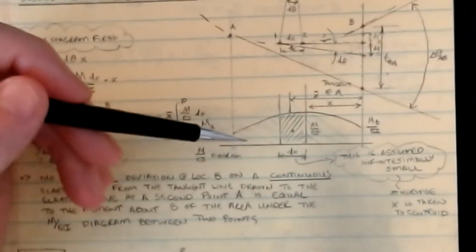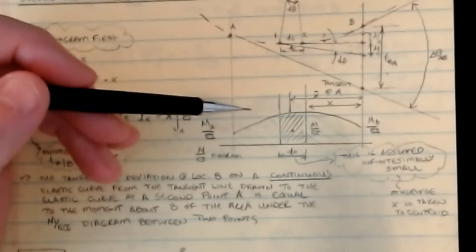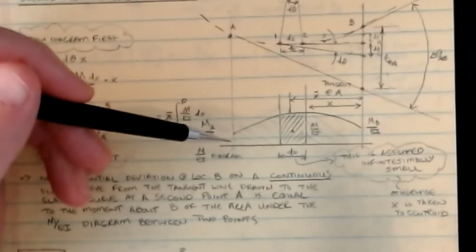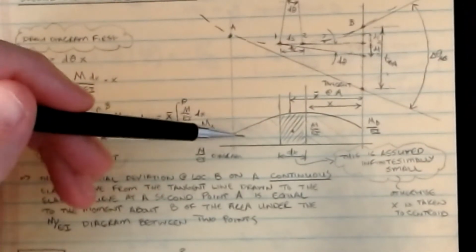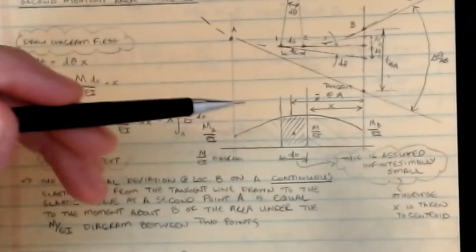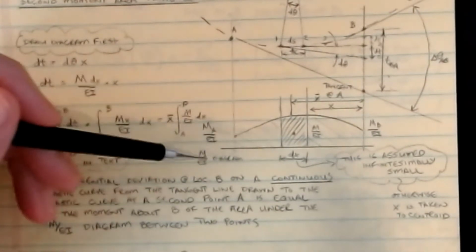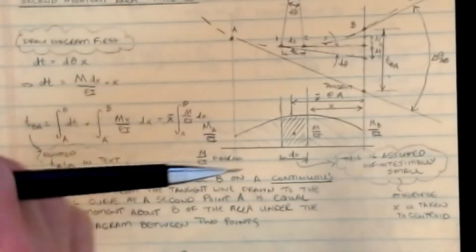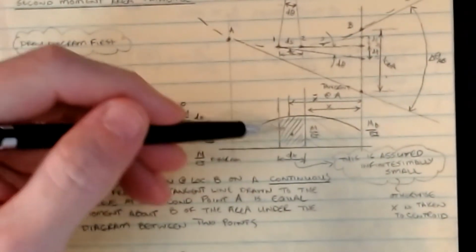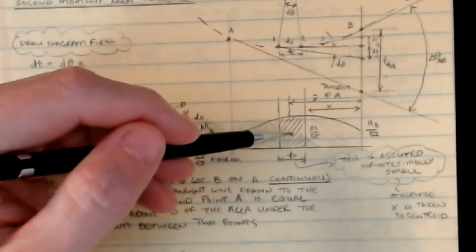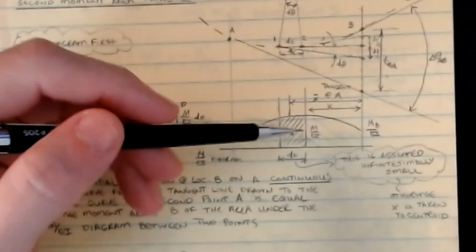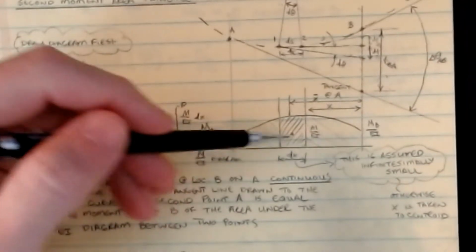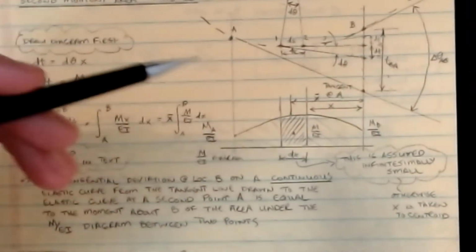So right there is our first potential problem that we have. The moment diagrams have to be something convenient for us to be able to work with. Otherwise, this method just becomes very, very cumbersome. It works very well for beams with lots of point loads where the moment diagram may be triangular, because I can handle triangles very simply. But if we get into higher order loads, then this curve and this function, trying to find the centroid of that, becomes a little intimidating. You can do it, and the method will still work, but it's not quite as convenient as when we have simple loads, point loads, and whatnot on our moment diagrams. Okay, all right, so let's give one a shot and see what we can do with it.